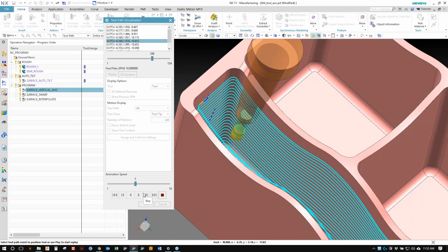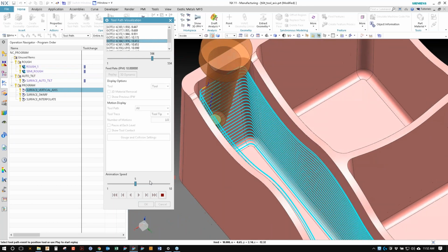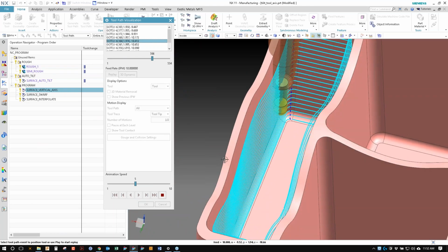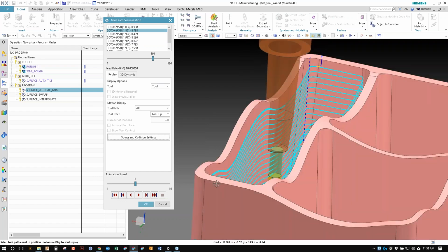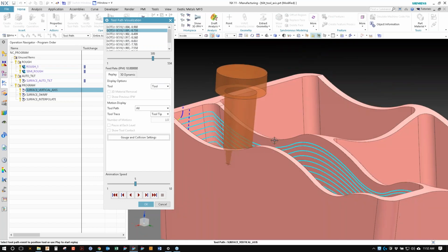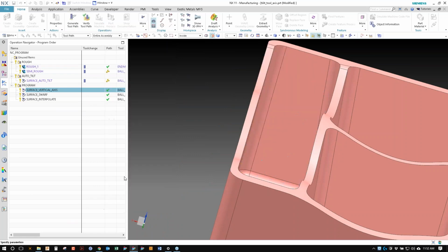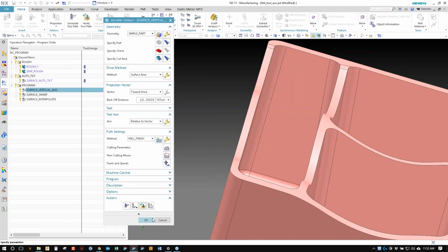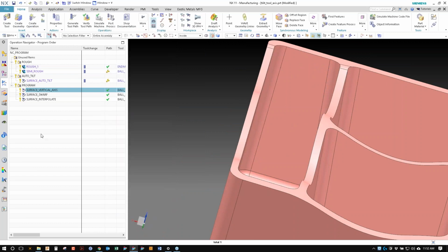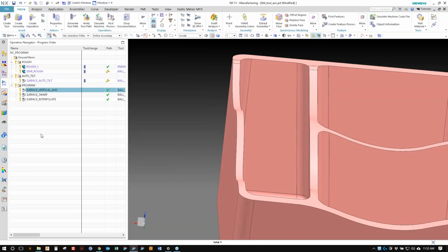Other than that, it's a good toolpath. The toolpath itself is smooth and also follows the contour of the part instead of doing air cuts across. All right, so once you have your 3-axis toolpath with collisions, you can use an already tilted one. I could also have used this on the Swarf that had collisions only in the corners.